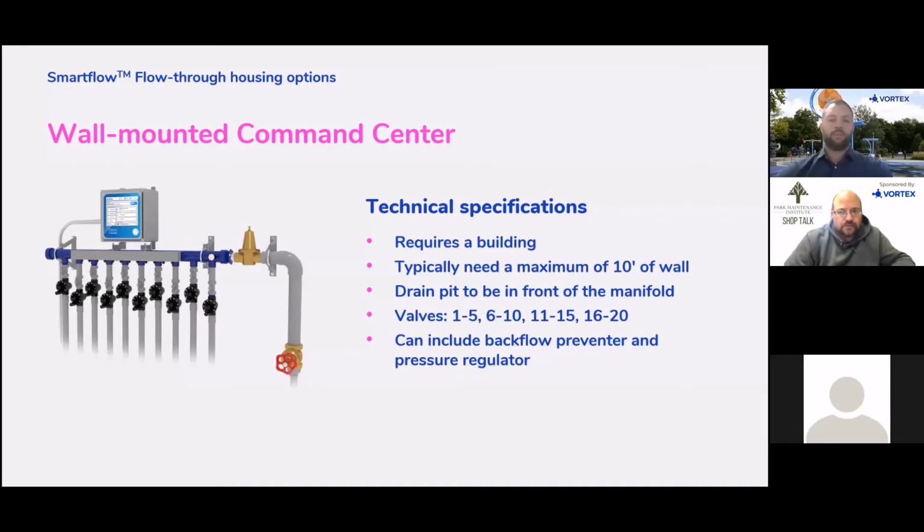If we have a splash pad that's using in the ballpark of 72 gallons per minute, that's going to be the max for a 2-inch line. Once we exceed 72 gallons per minute, we're going to be diving into either a 2 by 2 or a 3-inch supply, all completely related to water consumption. Gotcha. So the bigger the pipe, the more expensive the water bill. You got it.